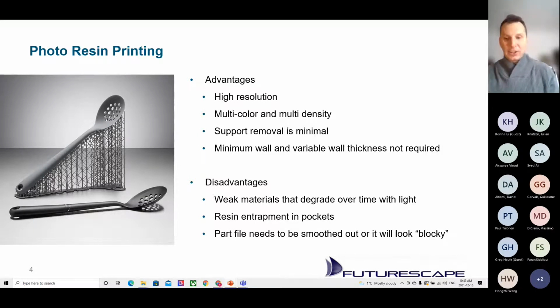One of the reasons why this technology, though, has not become more popular in the industry than it should be is the materials really are still quite inferior compared to the other printers. So they degrade over time with light. They have a smelly outgas, like a sweet, epoxy smell, and over time they become brittle. They've improved that a lot over the years by adding additives into the resin mix, but it still has limitations on the life of the part and the material restrictions.